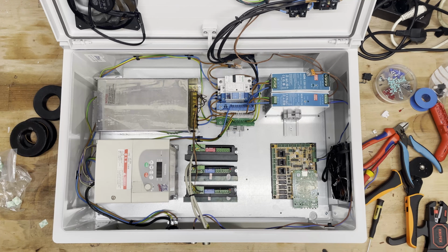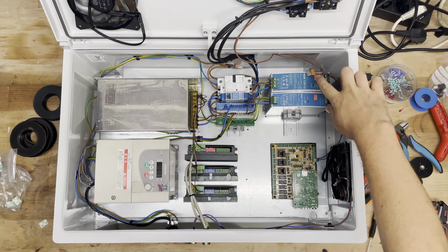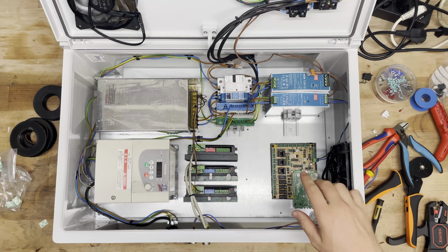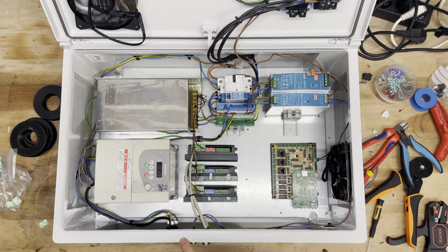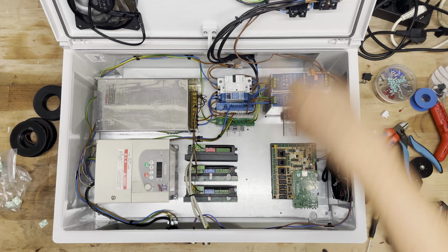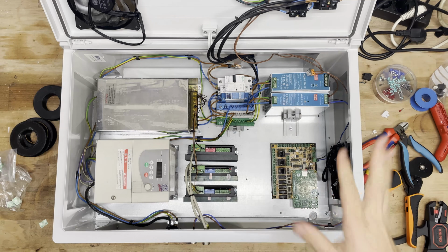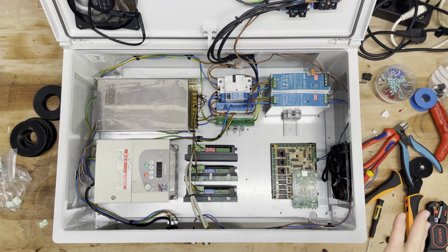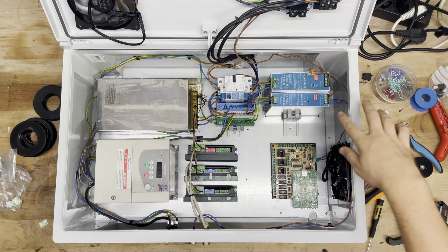So that was the 24 volt stuff. The only reason I have a connector here, and I don't know if that will be final how it is right now, is so I can disconnect the cables out of the control cabinet, because it's soldered otherwise on both ends and I didn't really like that. The other place it's just the Flexi-HAL that gets 24 volt and that's about it. So I will continue with 12 volt.